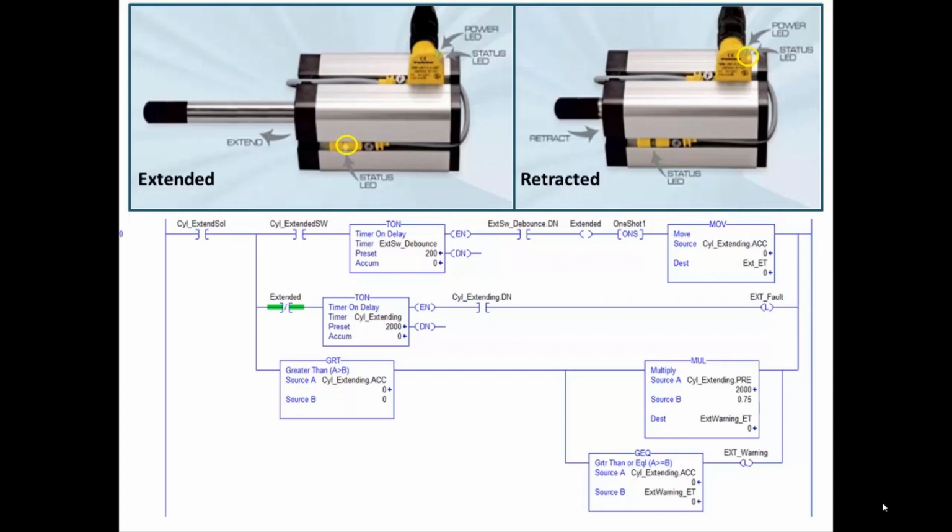Typically, when you're doing a project with air cylinders, it would be nice to include some diagnostics and put the status up on the HMI, the human machine interface. Most of the time, though, since it went to the lowest bidder, it did not include any hours for doing this kind of logic. If you could create an add-on instruction with the primary code already there, you're not really adding any real expense when you add this diagnostic capability. However, it does give you a competitive advantage. So let's look at the logic.